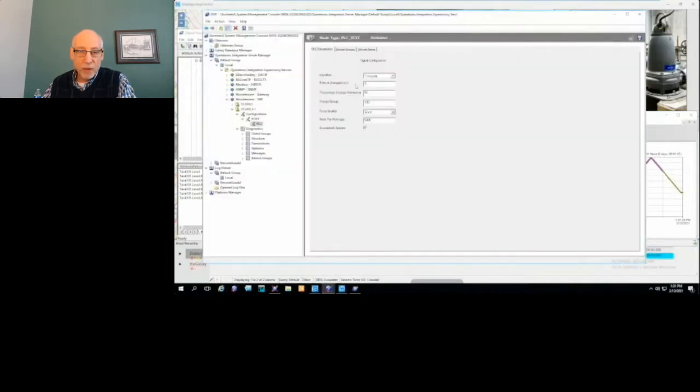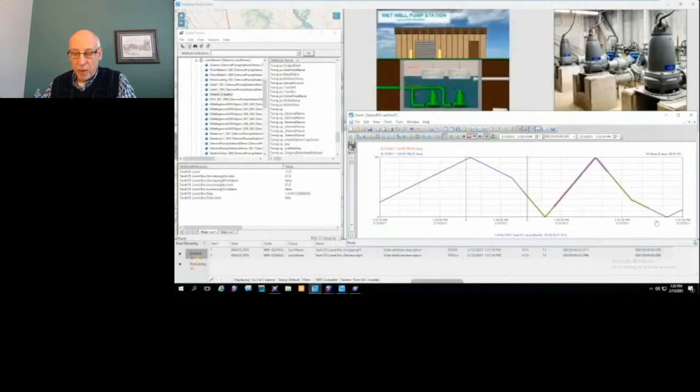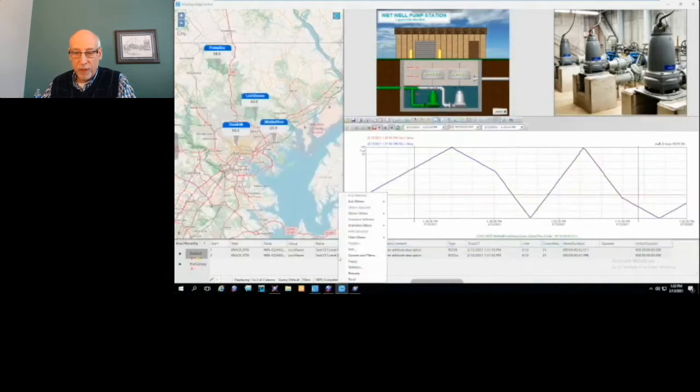So I'm going back into my simulator. We're going to put that back where it was, and then we're going to see where it goes out of the alarm conditions and back to the normal waveform that we had over there, and then generate that data. Right. So there it is. It's out of the alarm condition, and then it's back to where it was before. So again, great use case for the rate of change alarm to be able to detect when there's a slope change.